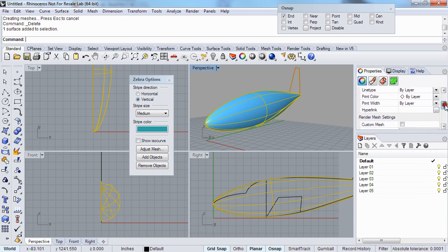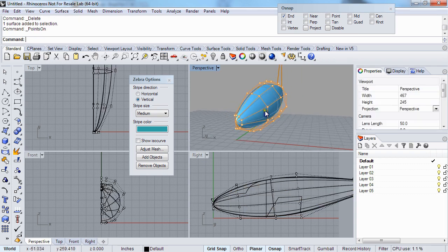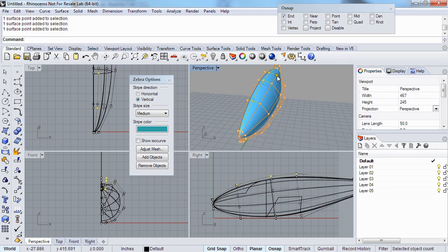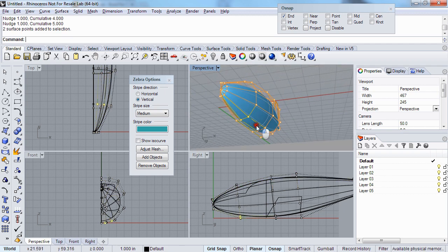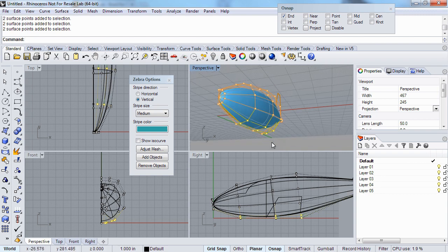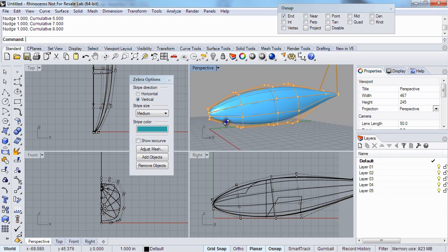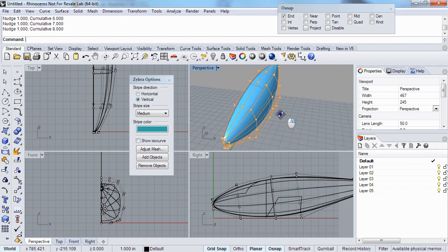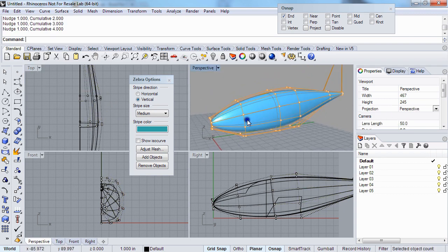And that's our input there. And what are the properties of that? I didn't see a setting for the... no, that's good. It's degree 3. So now I've got that, and I'm going to take some of these points here and move them around to make the fuselage a little more square around the cockpit area. And I'm mostly just using nudging, like so, a bit.